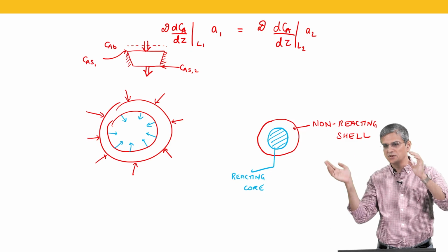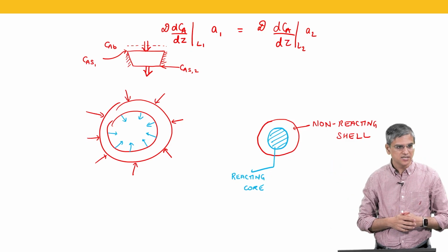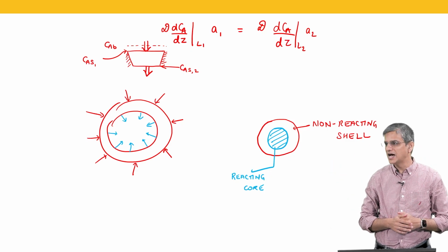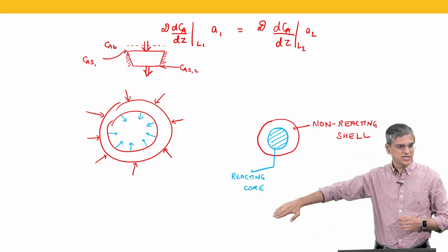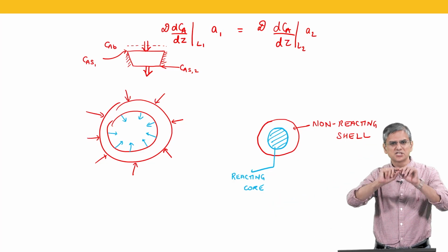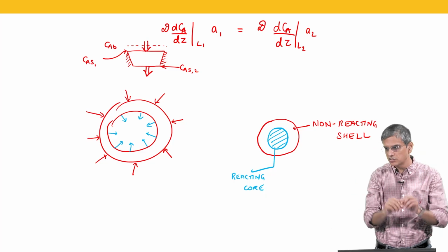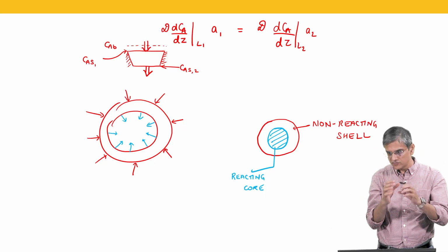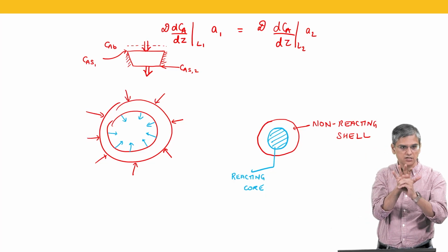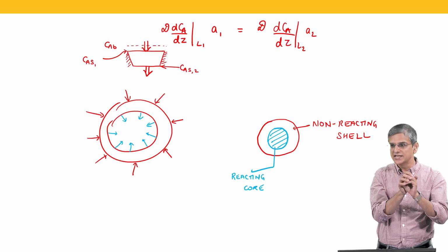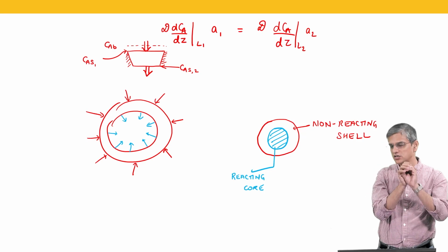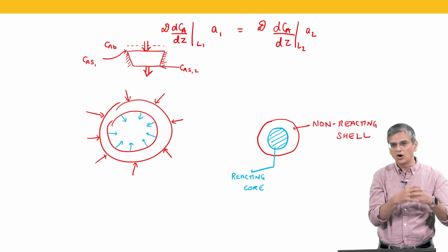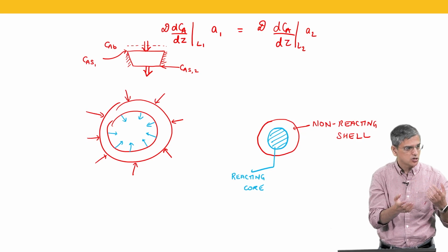If you remember what we did in Excel, for a very large slab, your concentration went to 0 very quickly. So essentially only the outer edge of the central blue region is reacting. That's when rate of reaction is very high, or diffusion is very low, or the central particle is non-porous.